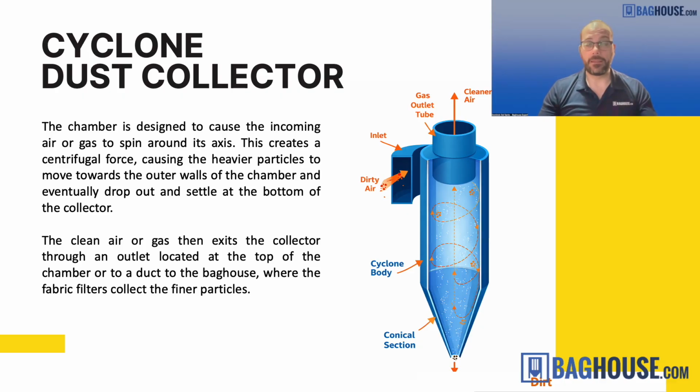So in modern day 2026, there is realistically nowhere that you can have a woodworking dust collection system of any notable size that goes to just a cyclone and then is exhausted to the atmosphere. It simply is not clean enough for the environmental regulations and also for safety reasons. Oftentimes we do still use cyclones in woodworking applications, but as a pre-filter, because they remove something like 90 to 95% of all the dust, especially the bigger particles, big chunks and strips and things like that.